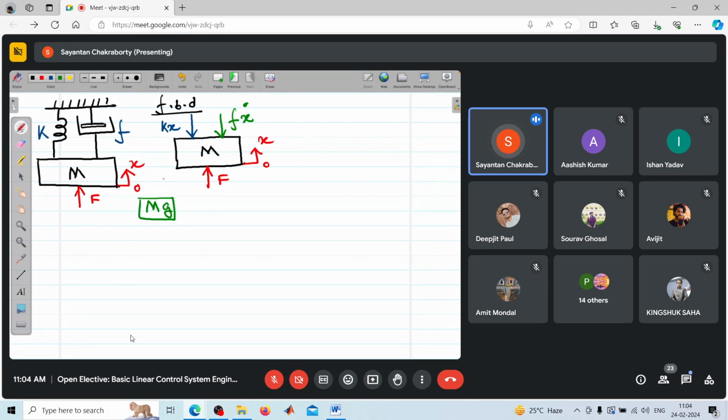Now as soon as you suspend the mass to counteract the weight of the mass, the spring gets elongated by say 0.5 inches. So the spring length has now become 12.5 inches, and that point is regarded as the point of equilibrium.